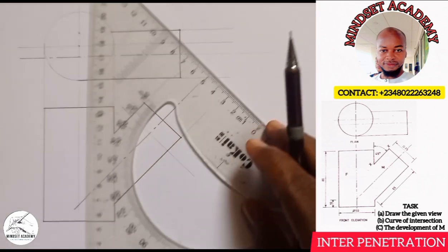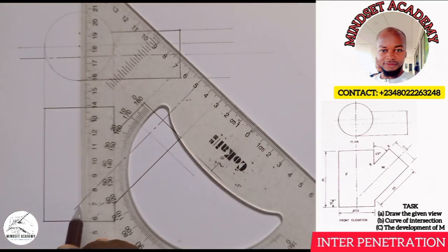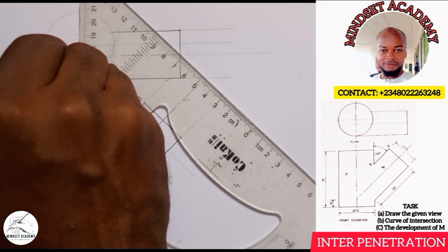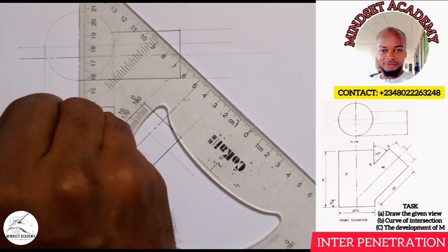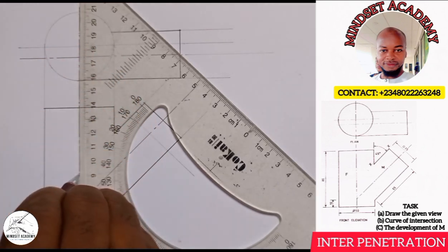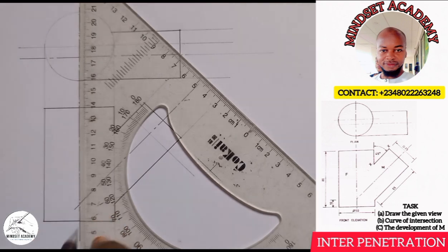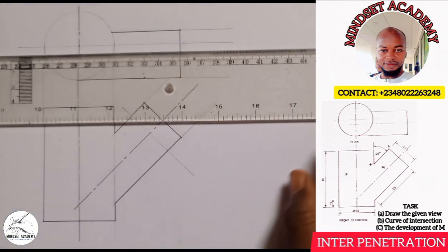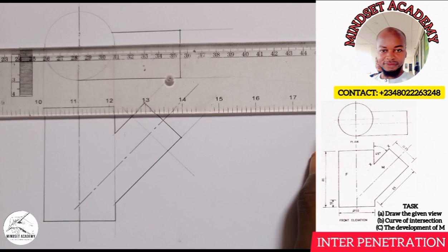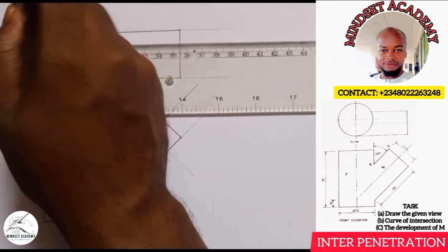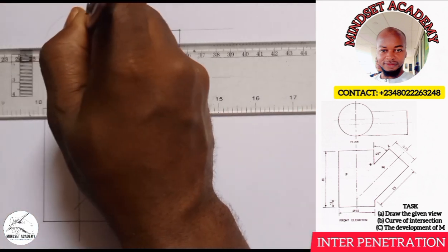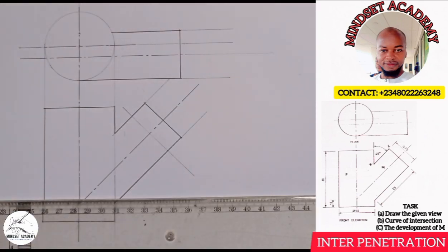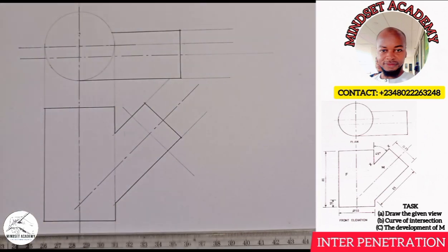This also here is still our hidden line, our center line. I can just complete it here. Long, short, long, short, long, short, long, short, long, short, just like that. Can you see that? And also I can just do this too. The main center of the circle, long, short, long, short, long, short, long. Hope you're good. Now we've done that.